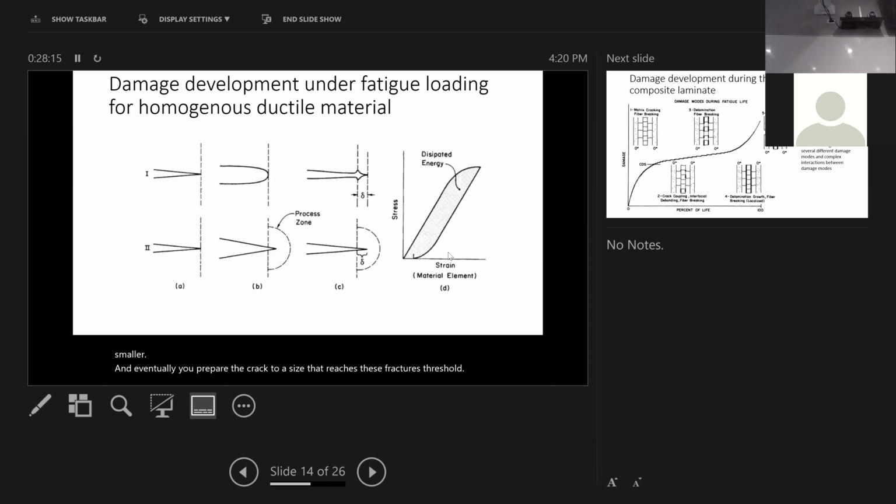The energy that drives the crack to grow is the mechanical energy input. The cycling energy is you pump the material essentially. Every time you cycle it, there's energy loss during the local yielding. You're loading, unloading, you lose a little bit of energy, as shown in the hysteresis. That energy is what drives the little crack forward a little bit every time. Later on, once the material breaks, you look at the cross section and you see the beach marks. The beach marks are those little increments.